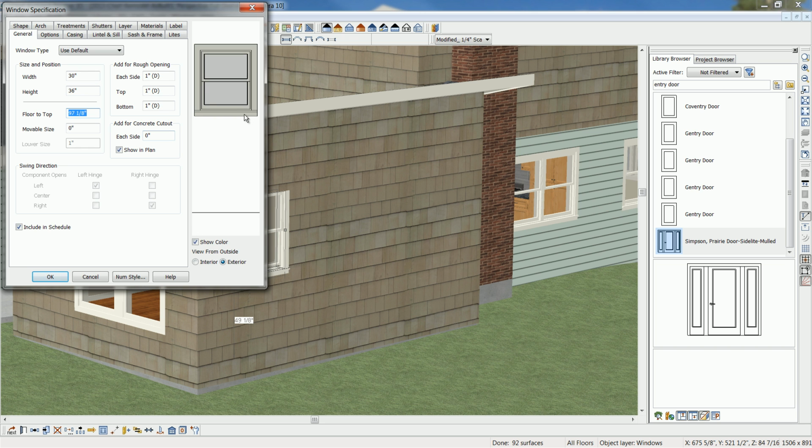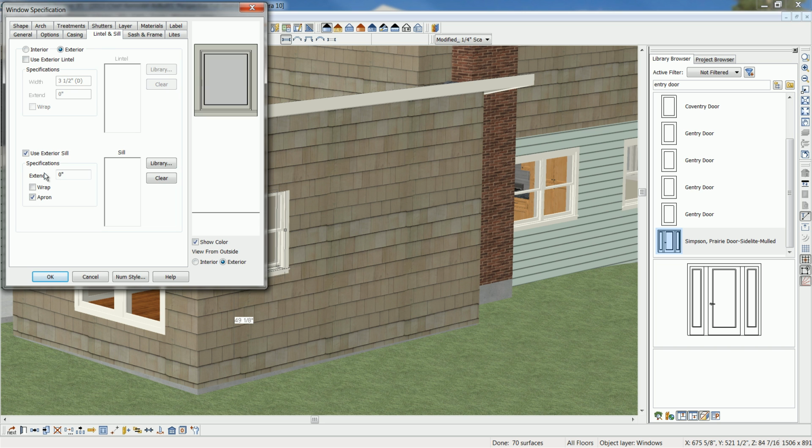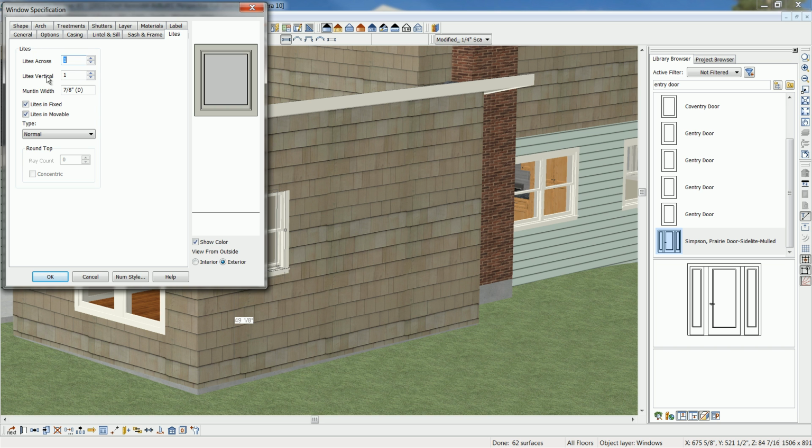And again, let's remove the sill and make it a fixed window. You'll notice different window types you can choose. Again, I'm just using a generic catalog window here. Fixed glass, come over to the sill, we'll remove it, add our few lights in here, and we'll make it a Craftsman style light. Once I'm okay with that, we'll leave that.